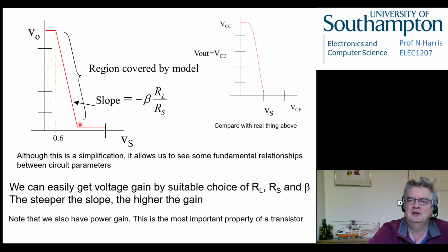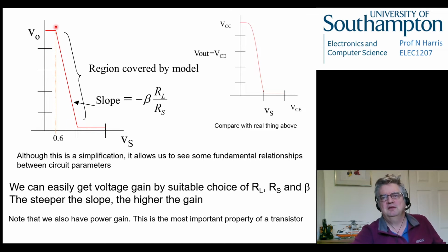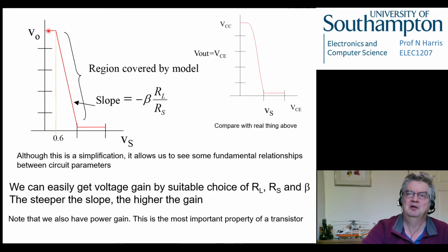And we can't go any lower than 0, so wherever it crosses the 0 axis, that's where it goes, and we know it's never going to get quite to 0, so we just add a little bit, 0.2 of a volt in there. So that's the equation of a straight line. The sloping bit is where our model actually applies. These bits at the end are where our model doesn't apply, and we've just applied a little bit of common sense to what happens in those kinds of areas.